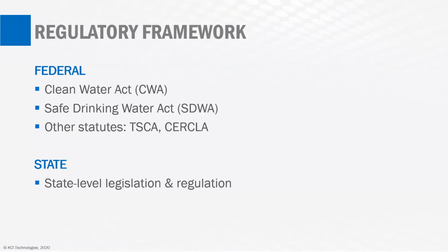Now, in terms of the time frame, they tend to run on a 5-year cycle. NPDES permits themselves are renewed in a 5-year cycle. And so for any individual facility to get a new limitation on a new chemical, it's probably going to take at least 5 years for that to work through. And that doesn't include whatever time it takes for the states or the EPA to establish the water quality criteria. Similarly, under the technology-based requirements, the categorical standards, every 5 years the EPA proposes new industries that they might want to regulate, and additionally they propose new chemicals that they may want to regulate. But it is at least a 5-year cycle from the time that they propose those until the time that regulations are actually promulgated.